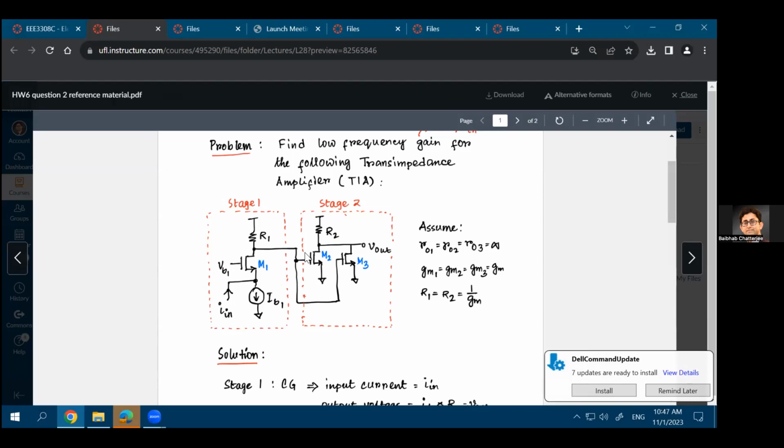You divide the complex circuit into multiple stages, and you already know how these different stages work. You already know what a common source stage is. You already know what a common gate stage is. You already know what a source follower is. Now you just need to identify what the different parts of the circuit do. For example, this first part of the circuit, again, is a common gate stage, because your gate has an AC ground. Any DC bias means that it's an AC ground, right? There is no AC potential in a DC voltage. So the gate is an AC ground, the input is provided at the source terminal, and the output is taken from the drain.